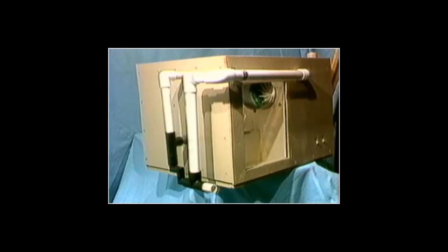How the CostGard Condensate Drain Seal functions can easily be explained by use of a simulated air handler. A small quantity of air is taken from the positive pressure side of the blower. A portion of this air is discharged through the condensate drain pipe to ensure that outside air and pollutants are not drawn into the system. The remainder of the air is directed through the mitered elbows into the air conditioning unit. The air pressure loss in these elbows ensures that the air velocity entering the condensate drain pan is too low to cause condensate blowing. At the same time, the seal allows condensate to flow freely from the drain pan.